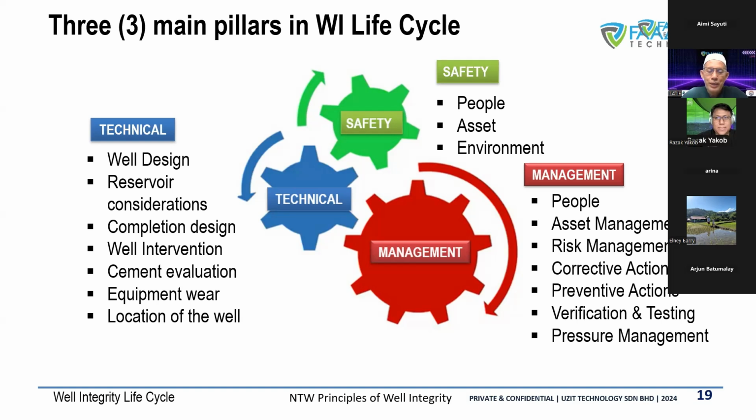For example, the well is stable, the open hole is stable, and then your BOP leaks. Then you say, oh, I have no barrier. No, you have cemented casing, and you have your hydrostatic. But your hydrostatic is temporary, so you have to do the BOP repair as soon as possible. Or, sometimes management will not agree; they say that no matter how stable you are, you only have two barriers, and if one barrier fails, then you are gone, because the BOP is being removed. So this is where we need to put a mechanical barrier, a bridge plug, about 1,000 feet or 1,000 meters down, and then you can nipple down your BOP because you have another temporary barrier. And for a temporary barrier during operation, a bridge plug is considered okay because you can test the barrier after that period of time. For example, your repair work will take about 24 hours. You test the bridge plug as a barrier; this plug should last maybe 1 month, but you just need it for 24 hours.